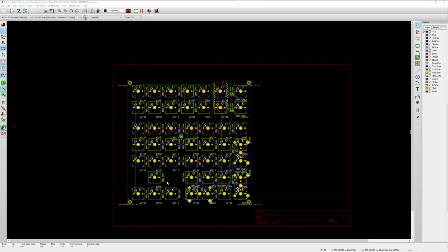Now, of course, if you have a lot more foresight and planning, you can probably do this a lot easier, because you would position your rows and your switches and the Pro Micro and its orientation to be hopefully as clean as possible. You can see the columns that I've done here, column 0, 1, 2, and 3 are all relatively clean, except for one crossover here, 4, and then 5 comes along the inside, which is lucky, and then 6 on the outside. But it's the rows that really get messy rather than the columns. So that's the completion of the actual trace component.